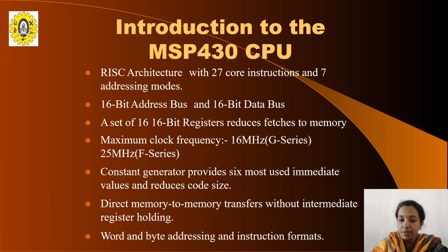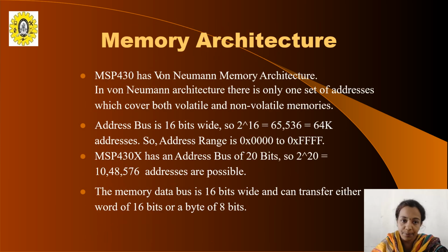Constant generator provides 6 most used immediate values and reduces code size. Direct memory to memory transfers without intermediate register holding will be there. Word and byte addressing and instruction formats will also be there.